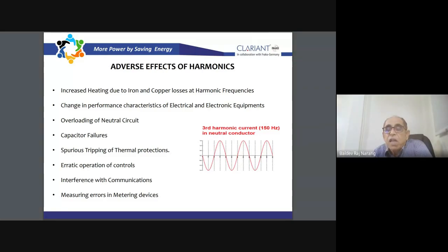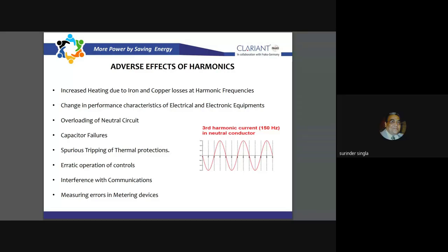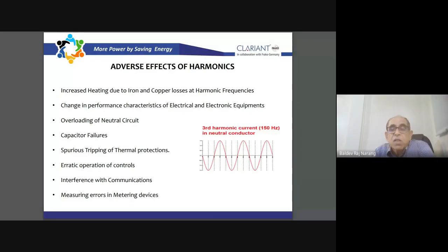So the cause is that third harmonic is caused by the unbalanced load only, and the voltage across the neutral depends upon the amount of unbalance only. Whatever is the unbalance, there is no correlation, it is a direct impact of that only. Is it a straight line effect or an exponential effect? No, it is straight only. There is no exponential or anything.